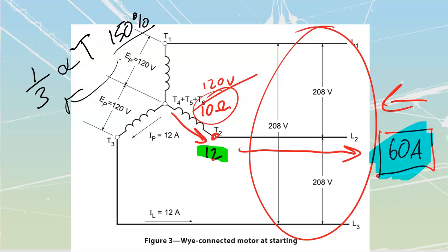Fans aren't moving a lot of air when they start up, so they're going to have a light load, or unloaded centrifugal compressor pumps. We will use these on large scale motors, but we would have to have bled the system off. If you've got a compressor that already has pressure in it, you wouldn't be able to start this up with that. It would just be too light of a torque.